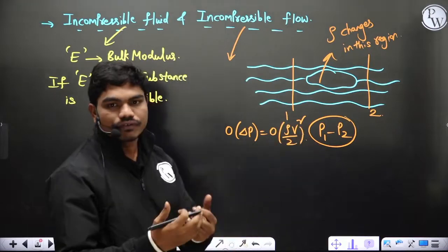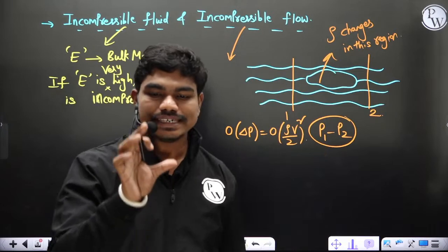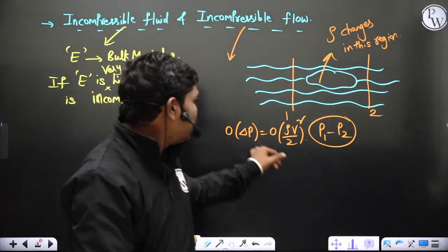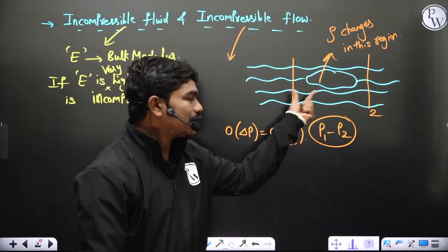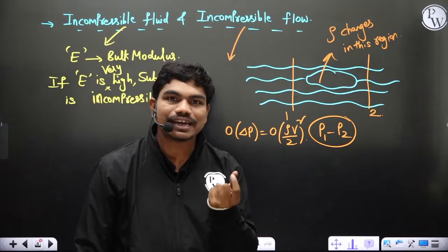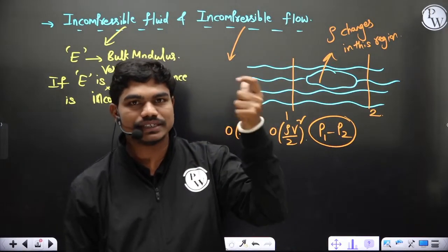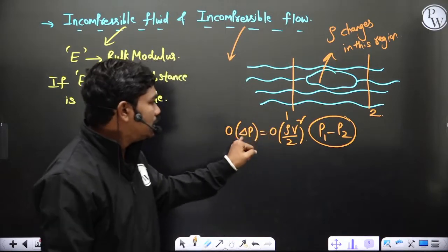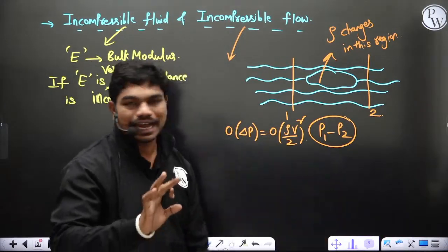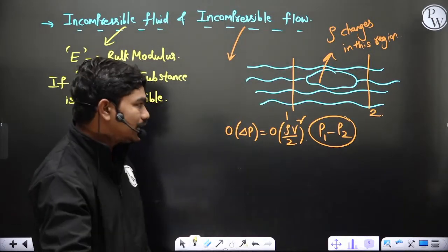Which of course, since you have already studied fluid mechanics, in Bernoulli's equation you will write P by rho g plus v square by 2g terms like this. So in general the change in pressure magnitude will be of the scale of kinetic energy. Many times you will even neglect the potential heads, because the contribution due to the pressure and velocity heads is very major in general flows. And normally if you do a bit of analysis, which I'm not doing right now, it's actually derivable, maybe in some detailed course on YouTube I'll take some time later.